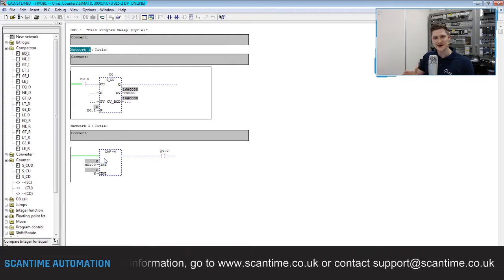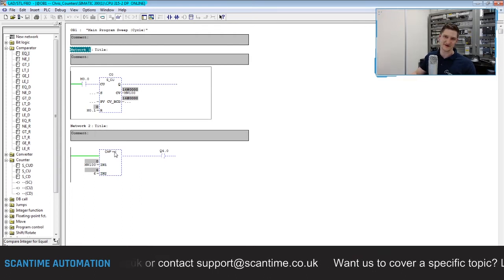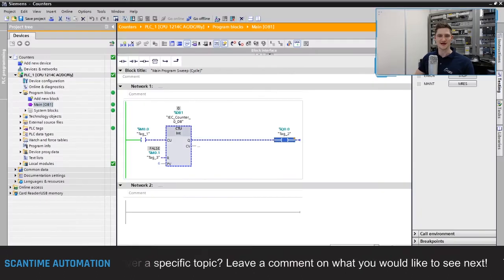Right, so that there is Siemens S5 counters. And like I say, you don't have to have this S, you don't have to have this PV, you don't have to have the Q. All you need is the count up, the reset, and the CV value, and then a comparator. So already you can start to see the downside of using counters inside of Step 7 as opposed to using them inside of TIA Portal.